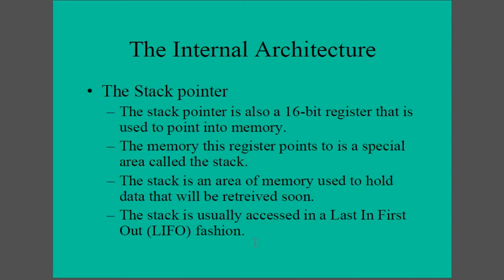For example, if you do a branch or an interrupt, you want to store the current program counter, the address you are currently processing, somewhere. The best place to store it is in the stack. That's why you need the stack pointer too, because you need to point to which memory location you store the data.